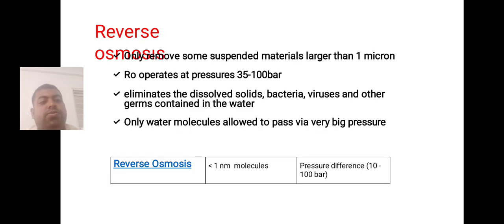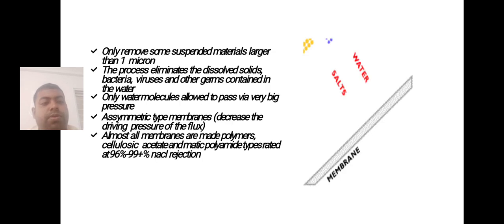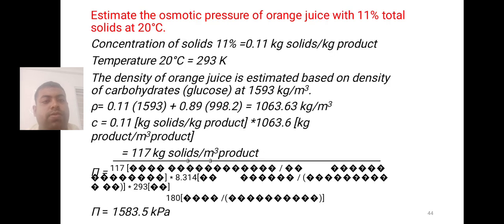It retains materials larger than 1 nanometer and it operates at 35 to 100 bar pressure. It eliminates dissolved solids, bacteria, viruses, and germs. Only water is allowed to pass through under the very high pressure. And this is the equation and the formula.